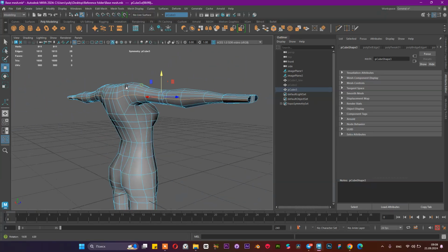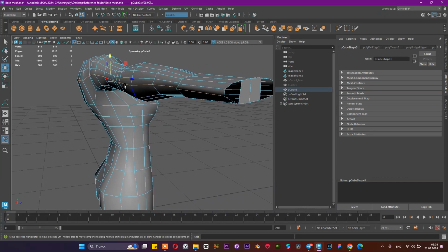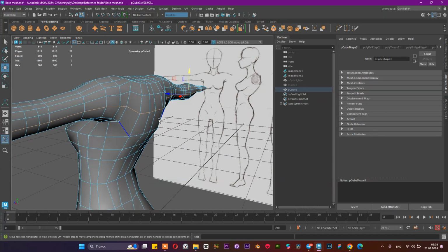And this edge I should slice a little bit down. We can use Shift, or maybe Shift Control. When I press Shift Control, you can see my cursor becomes slide. This slide tool is really useful when you need to move an edge a little bit according to your shape, for example not straight but a little bit round. I continue pressing Shift and Control, and you can slide this a little bit. This is a very useful tool to work with smooth geometry like a character. And if you learn how to move edges slightly, you can work better with your geometry.